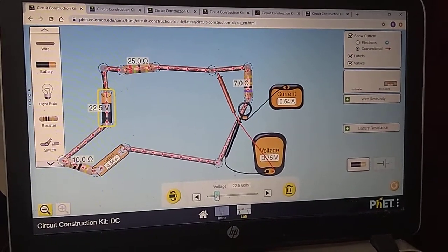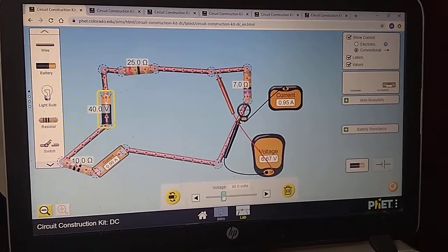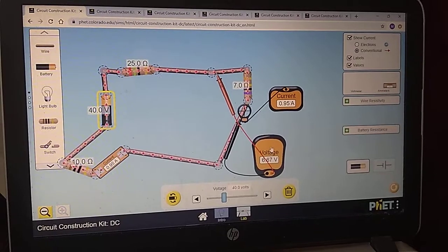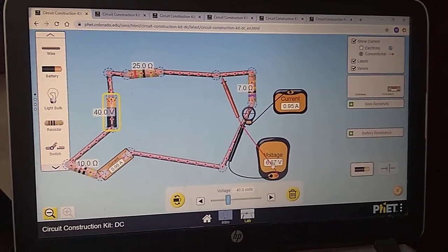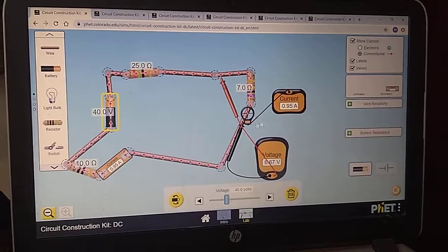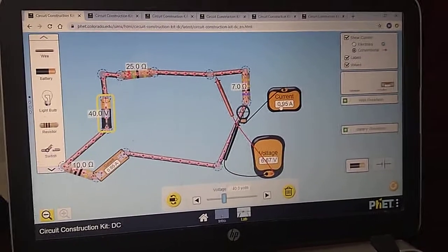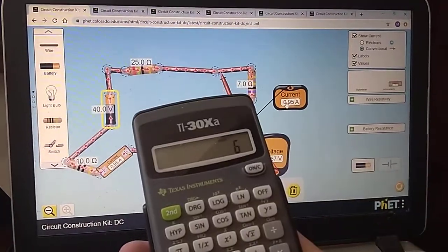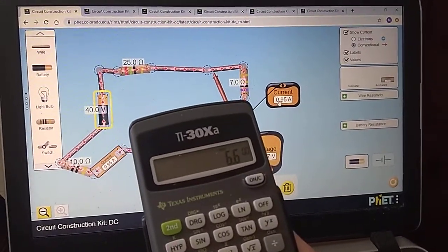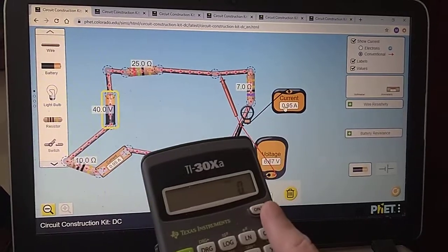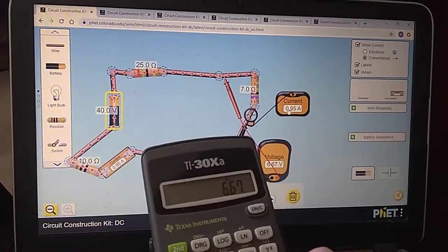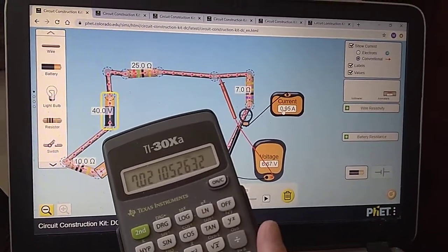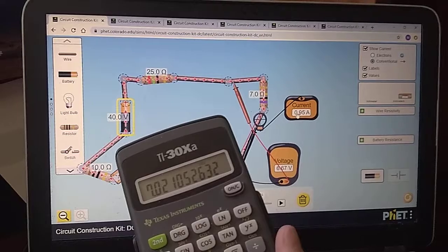Let's do this really easy. Let's double the voltage for the entire circuit to 40. Look at what the voltage drop for this resistor is now. 6.67 voltage drop, and the current is 0.95. Notice that they both approximately doubled. Now, if I take 6.67 divided by 0.95, notice I still get a resistance, the ratio of voltage drop to current, of about 7.